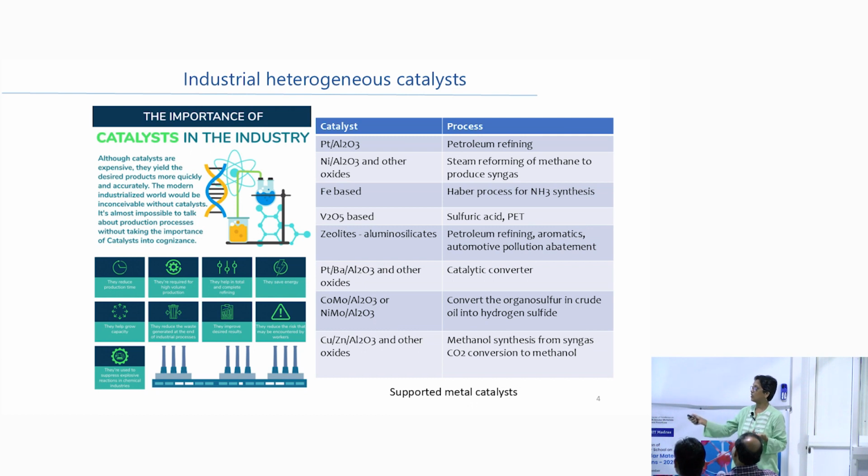They were working on this catalyst with Johnson Matthey. So the layering of platinum and barium and alumina was more important there, and that is how it works. And CoMo, NiMo, we call that. This is for desulfurization and all. Desulfurization is very important for us right now because of Bharat 6 and Bharat 4 and all that, you may have heard of, for diesel and petrol stages. There you have to bring your fuel sulfur content to 3 ppm, 10 ppm, like that, very low levels of sulfur. Otherwise, sulfur will form sulfur oxides and then acid rain, and all the other issues with that.